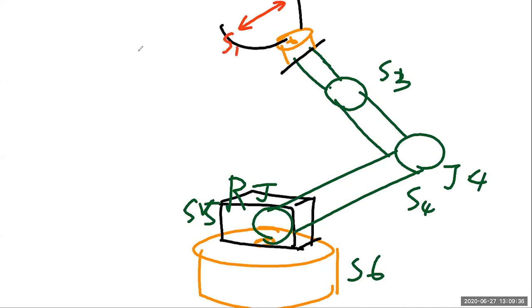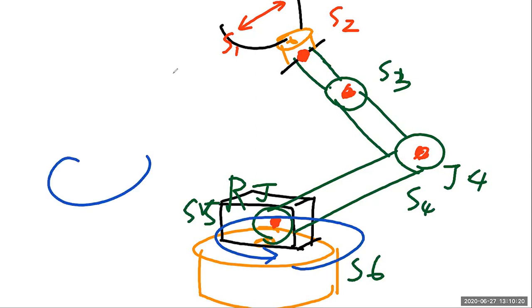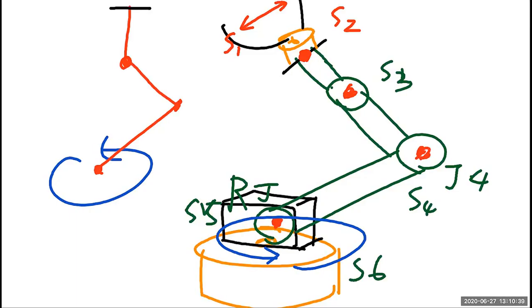Servo 1 for the finger actually has nothing to do with the kinematic diagram. And servo 2, the same thing. The end effector is over here, and it won't change, because your fingers have nothing to do with its motion. It's just open or release. So basically we have 3 revolute joints over here, and 1 does planar rotation. So 1 plane rotation, and the other 3 are perpendicular to it. So that is our robot model.